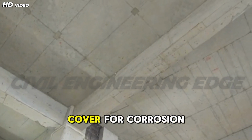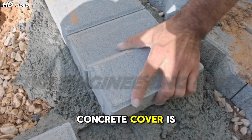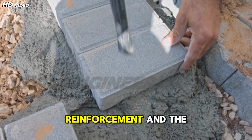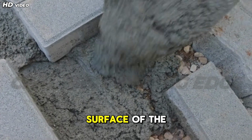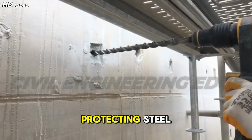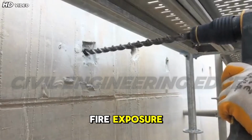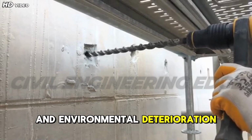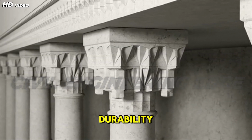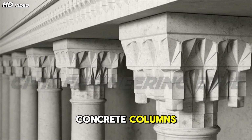Importance of concrete cover for corrosion protection and durability. Concrete cover is the thickness of concrete provided between the surface of the reinforcement and the outer surface of the concrete member. It plays a vital role in protecting steel reinforcement from corrosion, fire exposure, and environmental deterioration. Adequate concrete cover is essential for ensuring the durability and long-term performance of reinforced concrete columns.